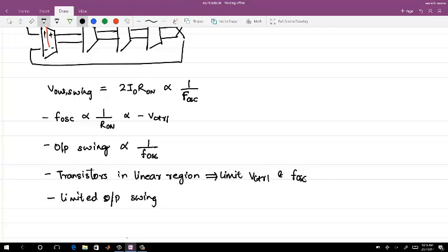You're using these clock outputs to clock some digital logic, which can have a variable input clock frequency. But if the amplitude changes, you need to design the whole logic as per the changing amplitude. And if your amplitude is inversely proportional to oscillation frequency, you get more susceptible to noise at a higher frequency.